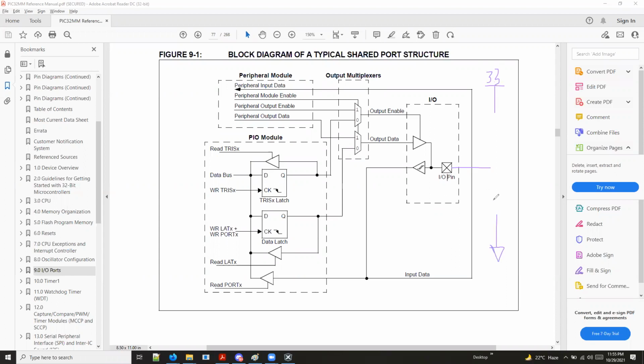To input ground, let's say we can have a switch here that, when pressed, sends ground to the pin so the input is low. And then when we want high, we can put a switch here, and that is the way to make our input at the pin high. But the problem here is that we need two switches. So what can we do to halve our switches?